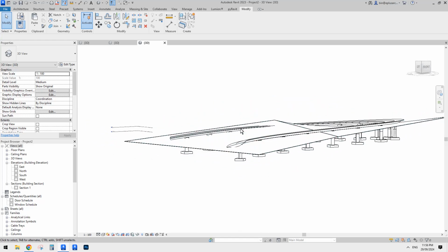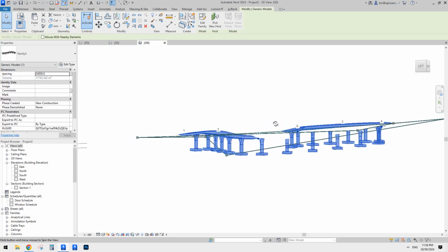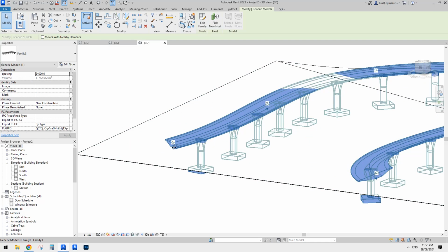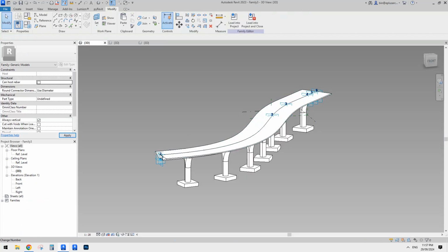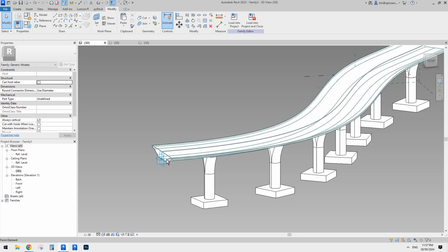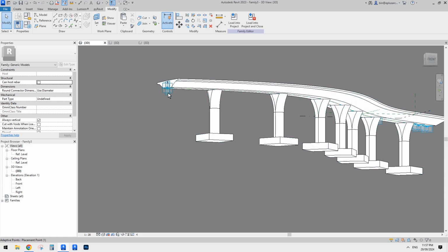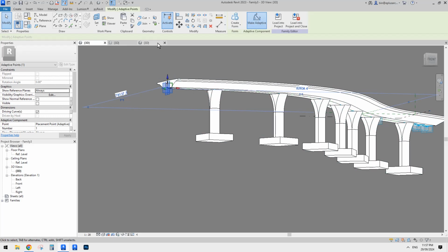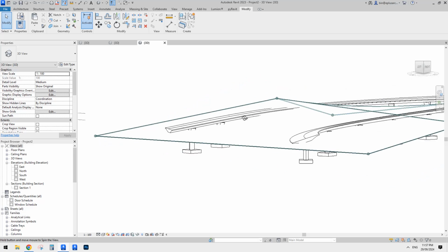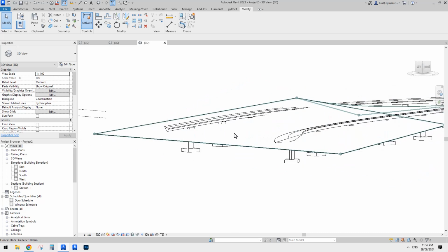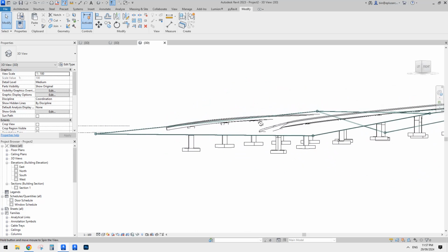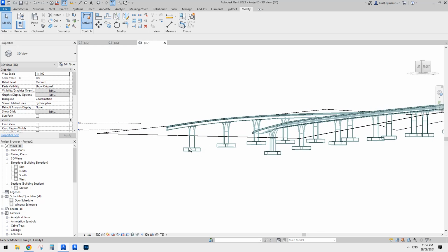So okay, now we have some issue, right? Because when we model this, we used the underneath of this surface as the base. So when we place all the adaptive points, this will be placed in the ground, right? So if we place onto the floor, ideally we want to directly place this column on top of this floor.